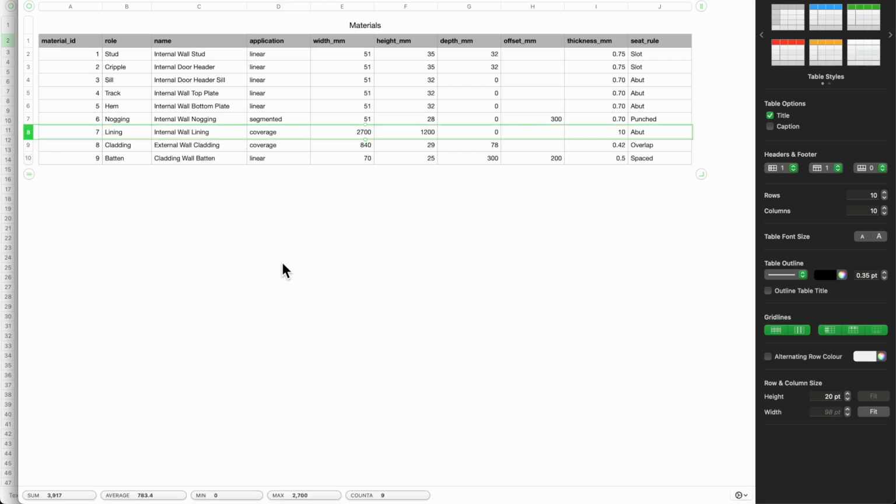And just to give you an example of where it's going to be different, as to why I went into so much detail: plasterboard is usually laid horizontally, but I don't have the stud layout for top to bottom horizontal, so my plasterboard's going to have to be laid vertical. And there's two reasons. The face of the nogging section is only 28 high.